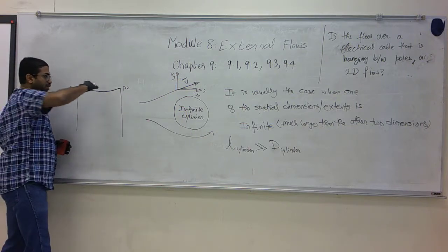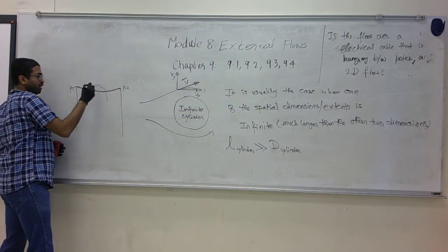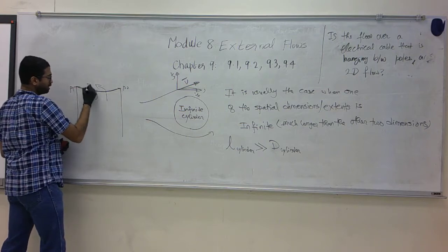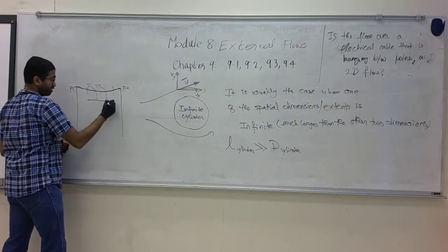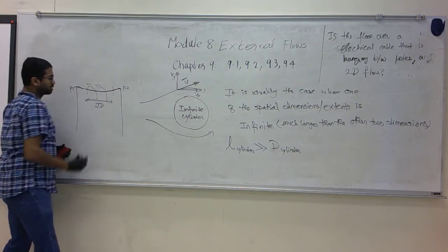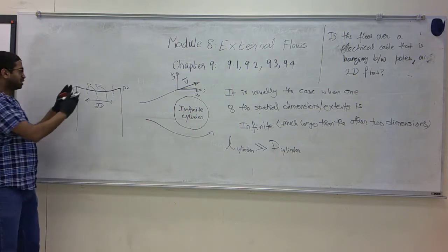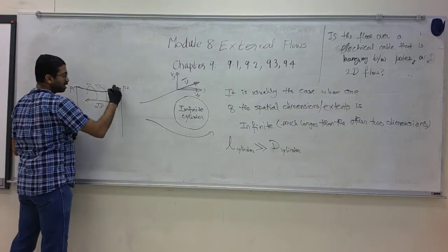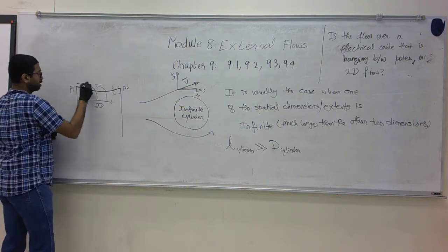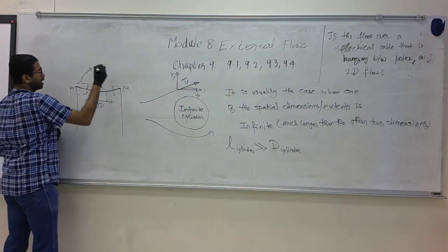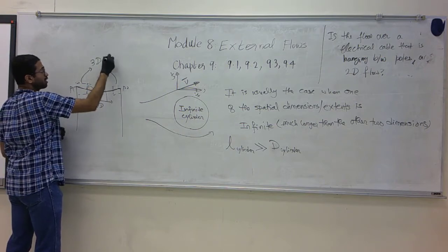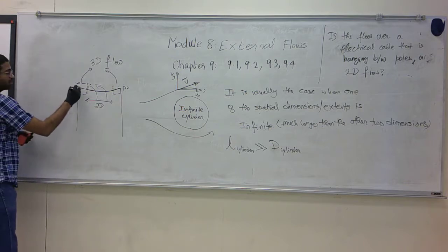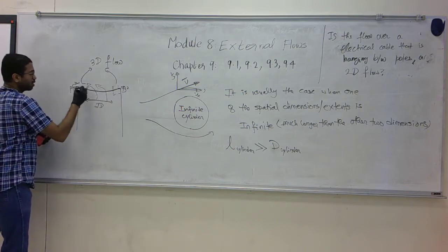And let's say the wind is blowing in this plane, the wind is blowing over the pole. If I am considering regions that are reasonably near the middle, over here the flow can be considered 2D, because they are far away from the edge. The length is much longer than the diameter of the wire. If I am considering these areas near the edge, at these locations, it has to be considered a three-dimensional flow, because the flow here is dominated by the flow around the pole, not only over the pole.